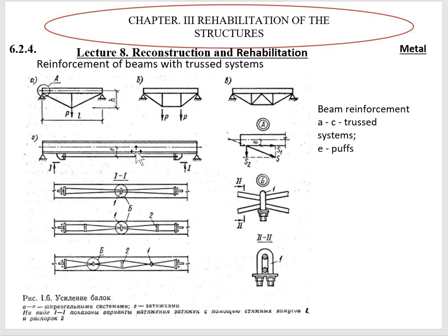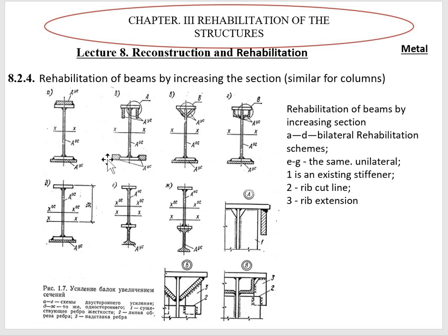And in this way we can see the addition of prestressed elements, a rod element. So we weld it right here. We heat it. Under the impact of heating, it enlarges and becomes longer. Then we weld it right here, and when the temperature comes down, the length of this element becomes less, and it gives prestress to this beam.